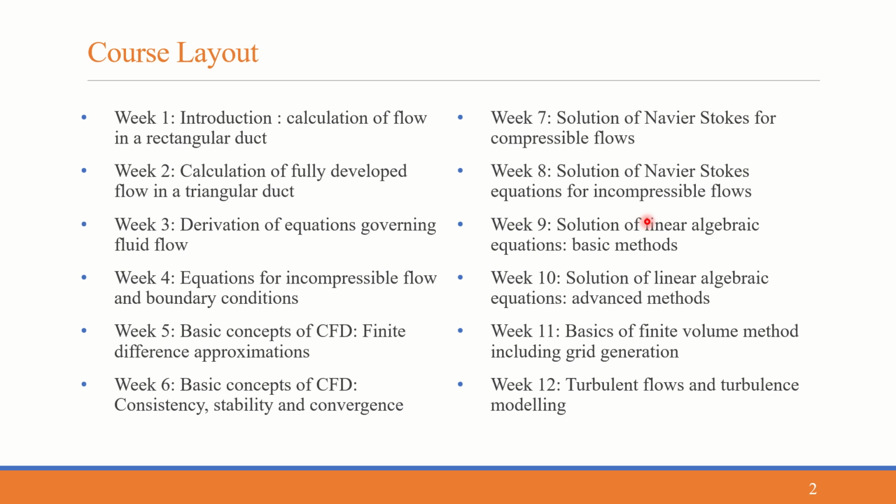So there are various techniques proposed, including Reynolds averaged Navier-Stokes equations and so on. Those use certain closure techniques. If you do not want closure techniques, you need to go with direct numerical simulation, which is again computationally very expensive. So again, it depends on what our ultimate requirement is and what we are willing to sacrifice.